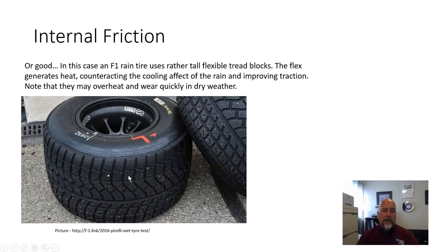When these tires are driven around the track, that rubber will tend to flex quite a bit. And that helps the tire warm up and soften to maximize the traction as much as possible. Now, the reason for all the grooves is to displace the actual water, so we can warm up the tread, and it can cut through the water down to the asphalt underneath and give a good amount of traction.